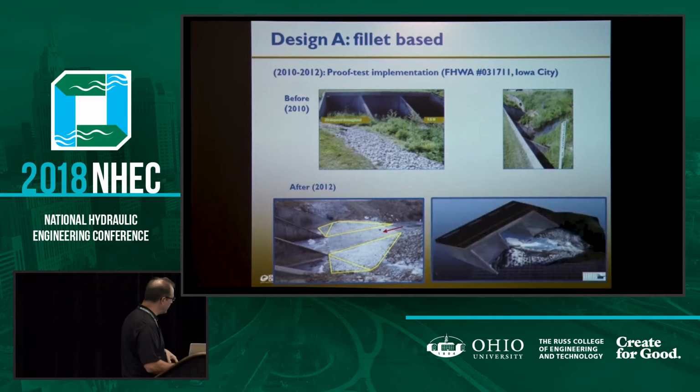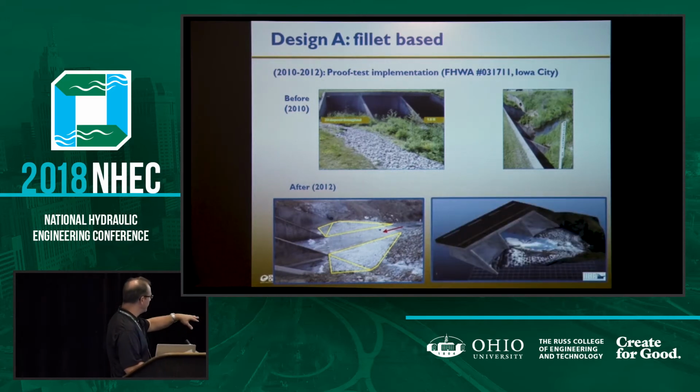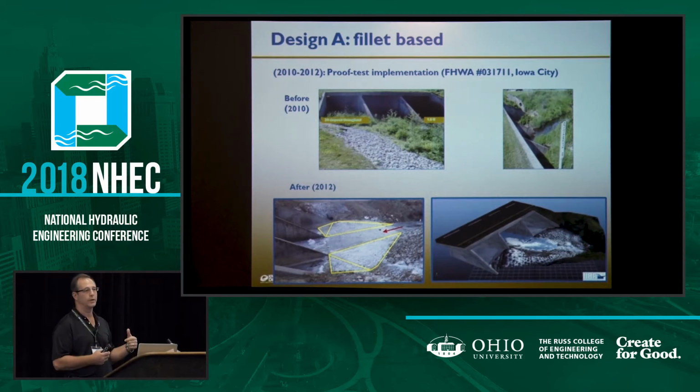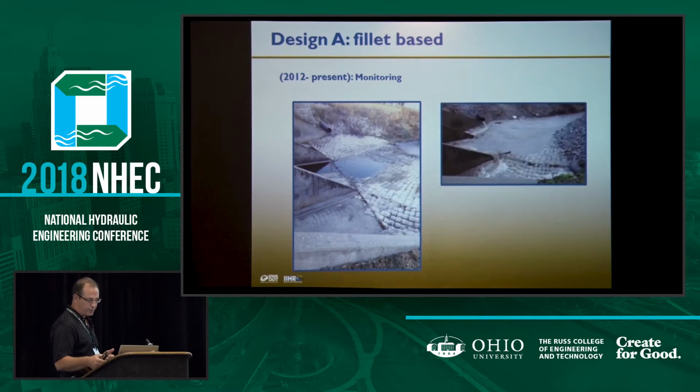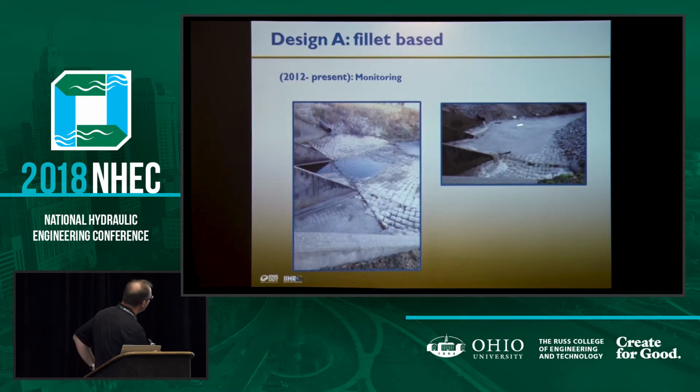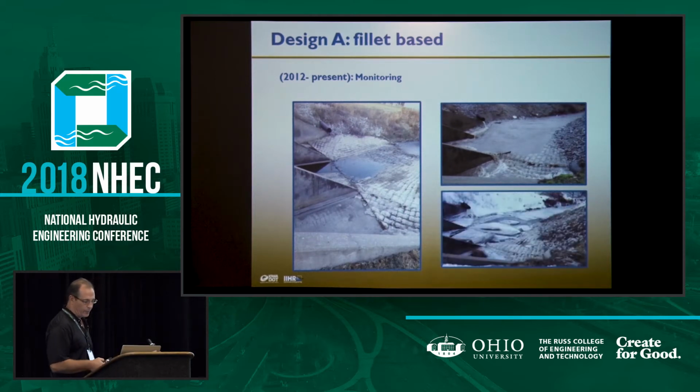And these wedges then create a situation where the flow is accelerated through the outer barrels, and we think it will help reduce the sediment process in those outer barrels. So this is in 2012, right after construction. This is an event going through there. You can kind of see the water accelerating through here instead of being recirculated, right? So it's kind of proving out the results of what was in the model.